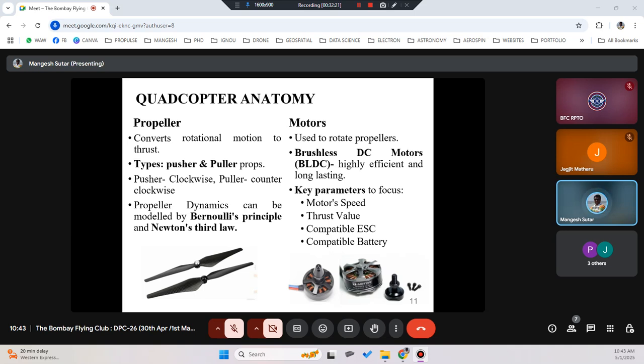Okay, so got it? What I'm trying to say is that the first component is the motor, and that is the defining factor of the drone. Once you decide what motor to use based on its weight capacity specification, you will design whether you are building a quadcopter or hexacopter. A lot of the time, octocopters are designed in a quad format also, so you have two motors on the up and down side. That's why you double the thrust.